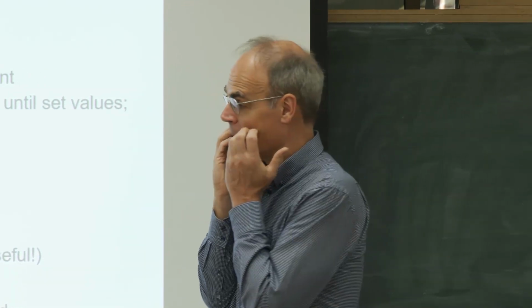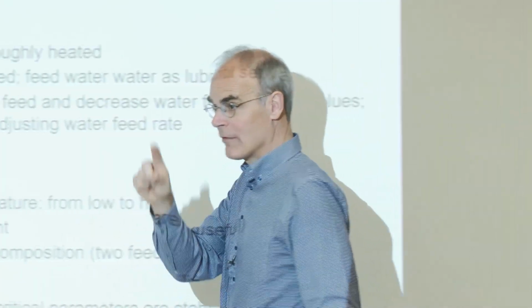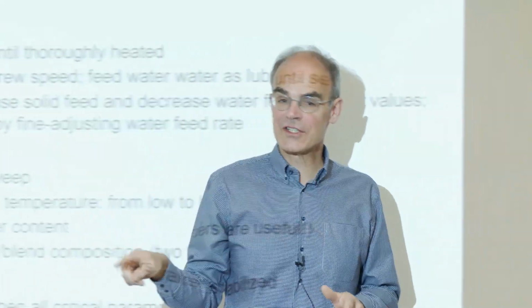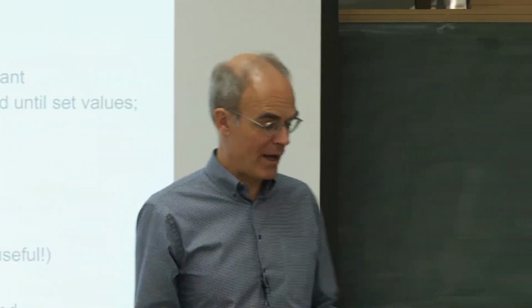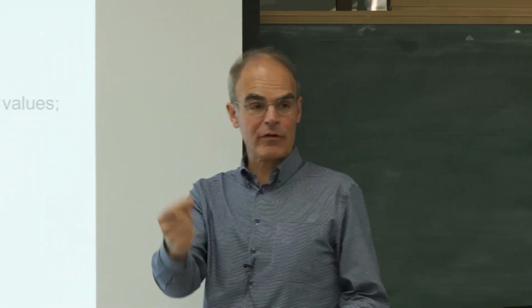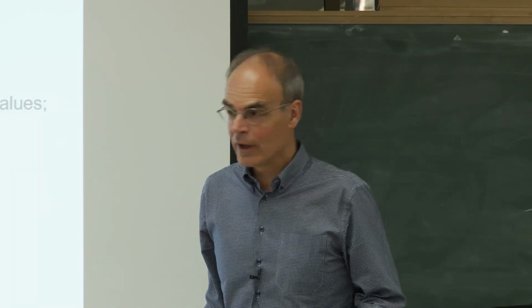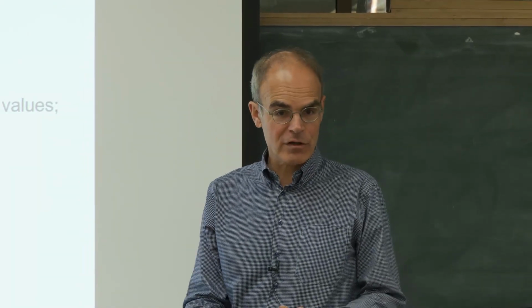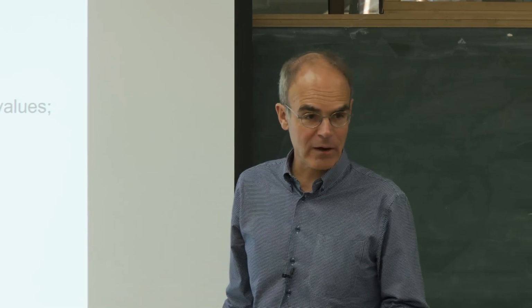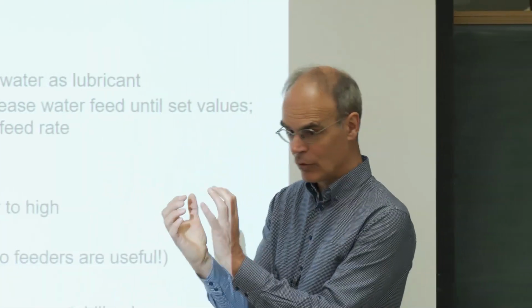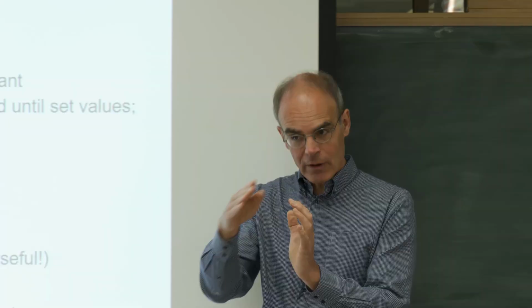Actually, our extruder for the low moisture die should have a separate whole cooling system, an oil-based cooling system, that we don't have. So heating it up is like that. Cooling it can take really long, because we do it now by forced air. We just blow air through the cooling mantle there, but it comes down really slowly.